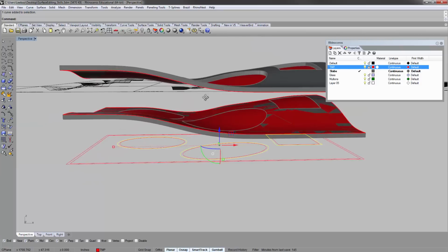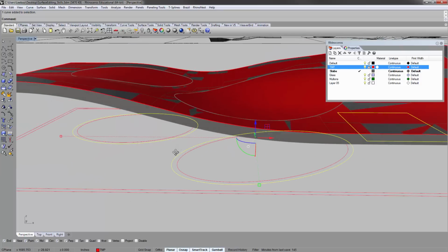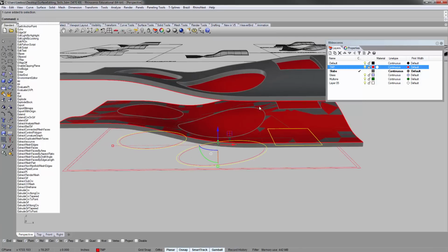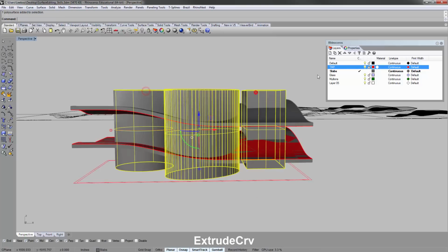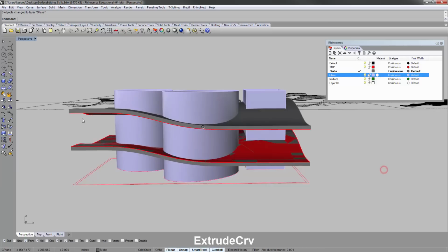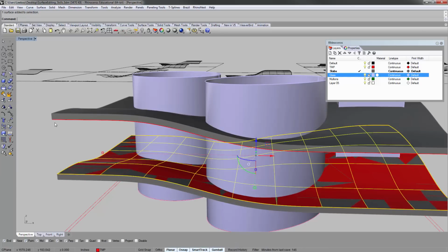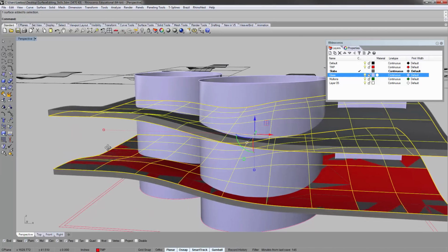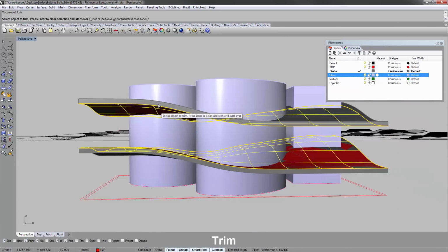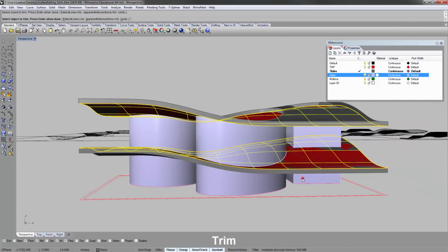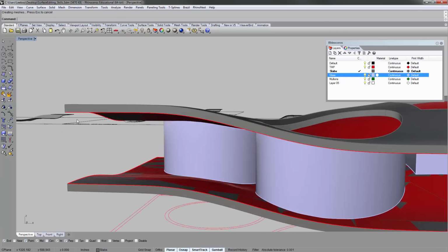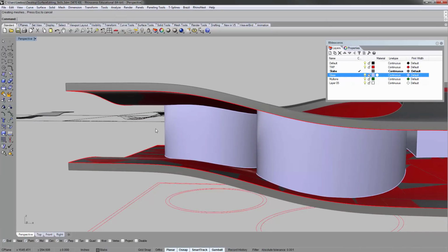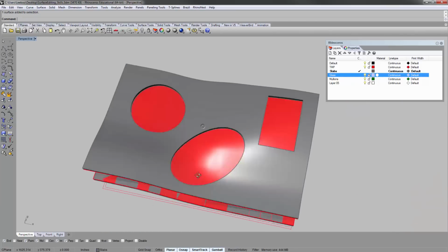All right, so let's take those outside offset profiles and extrude them. Same thing. You can change them to glass if you want. Take those two cutting surfaces to trim out top and bottom. Okay, so I mean, you have to be careful of this, like I'm using the sandwich, right? So these actually only extend to the inners of the slab.